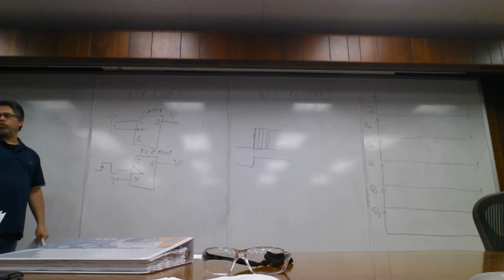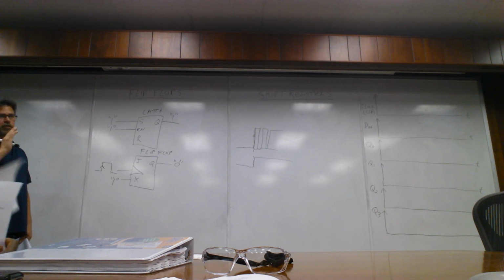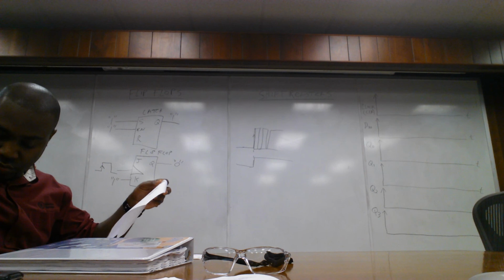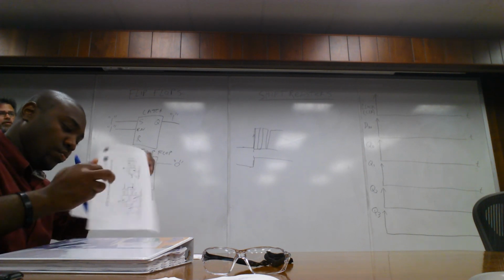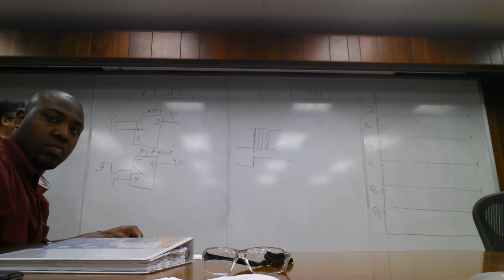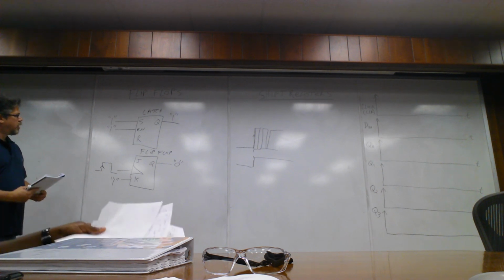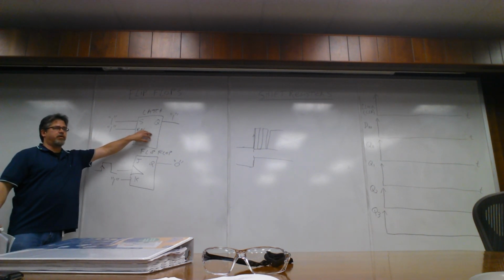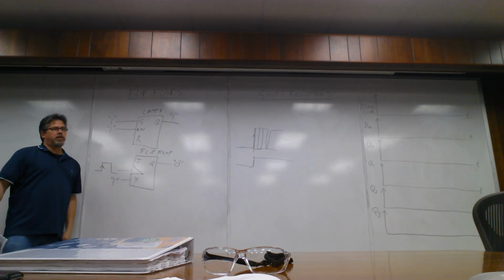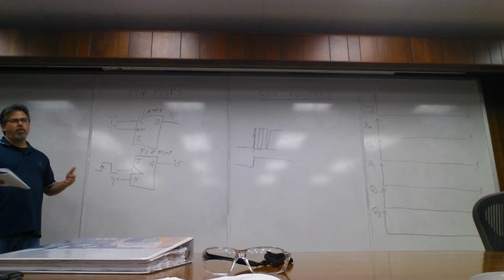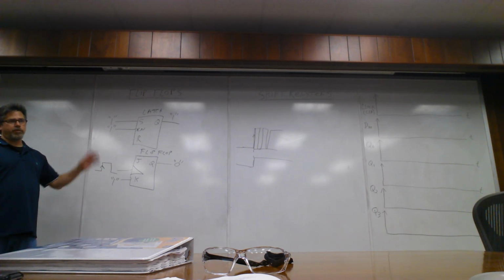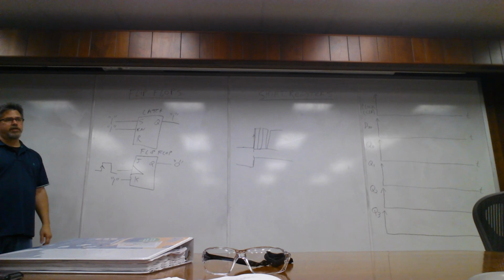The microprocessor wants to run at a very quick rate. It wants to pull that data and then just do some processing. So you want to capture the first sequence of changes on some kind of input device, and that's what the latch does. It holds the data there for a period of time. You can consider it like a sample and hold arrangement, which we'll be talking about later on for sampling.